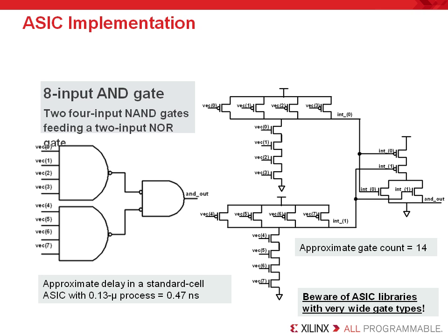So when we build this 8-input AND gate into an ASIC, we are essentially building with 2 4-input NAND gates to get a wide function. But as you know, this implementation will vary by ASIC vendor technology. You may have to build this with a wider NAND gate depending upon the ASIC vendor.